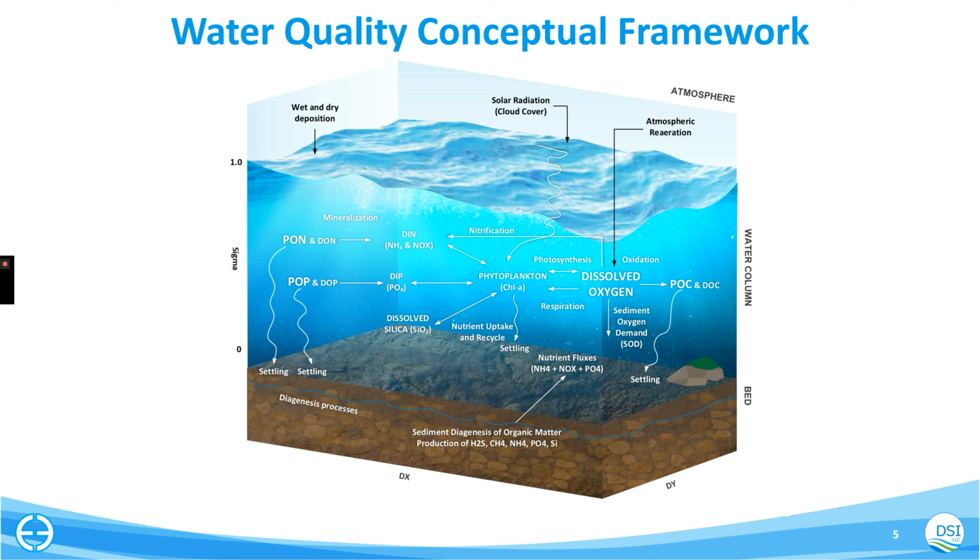But anyways, it's a surface process here. And then the effect of solar radiation and light attenuation, which affects the heat submodel. In EFDC Plus, we've coupled the algal components and organic carbon components into the light extinction, so it's a much more dynamic process calculating light extinction, which affects the growth of your plankton.